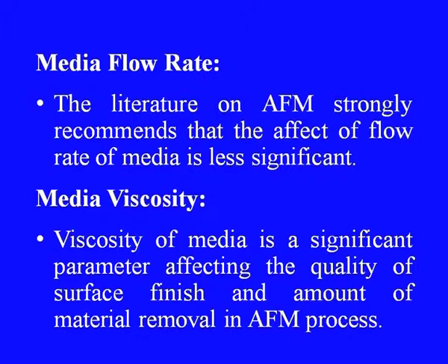Media flow rate. Literature on abrasive flow machining strongly suggests that the effect of flow rate of media is less significant. Then, as far as media viscosity is concerned, viscosity is a significant parameter affecting the quality of surface finish and amount of material removal in the abrasive flow machining process.